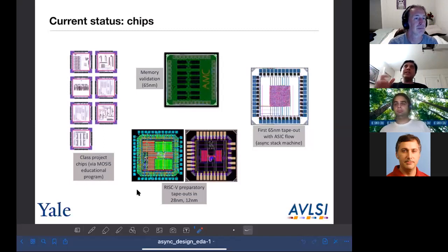So essentially the idea is you use this dynamically. You have a cache essentially of your existing cells. And if you have any new logic family, then you add to that cache and you build up your library over time as you need it. So that's essentially how we do it. And we have our own characterizer, so we can characterize all the cells that you just built. Once that cell is in your characterized library, then the next time you run anything that uses any of the cells that you already have, it'll just pick those up and use them.